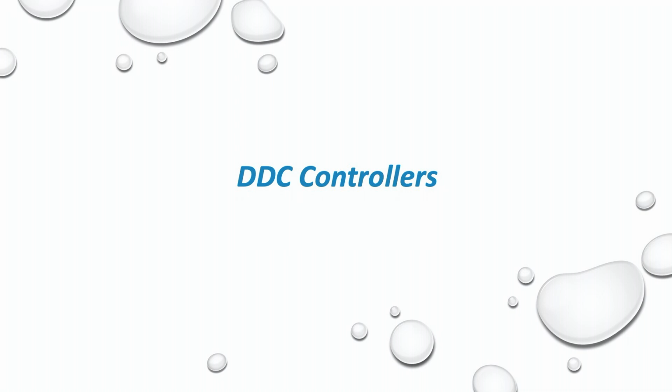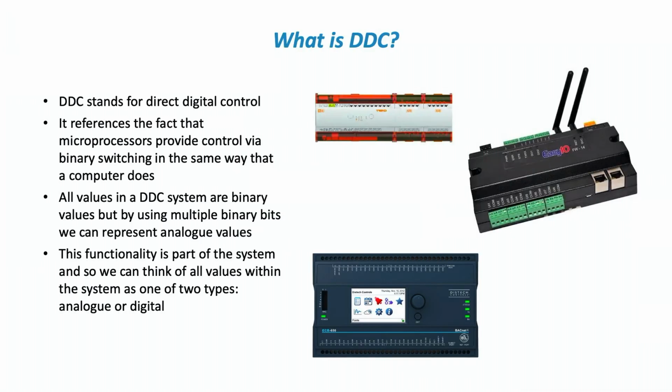DDC controllers, direct digital control controllers, bit of a mouthful. It references the fact that microprocessors can only control using binary switching in the same way that a computer does. This used to be an issue when I first started doing BEMS because of the resolution of binary switching. It's really not anymore. But it is important to understand that these are computers. So when we're performing our mathematical functions, we're looking at binary values.